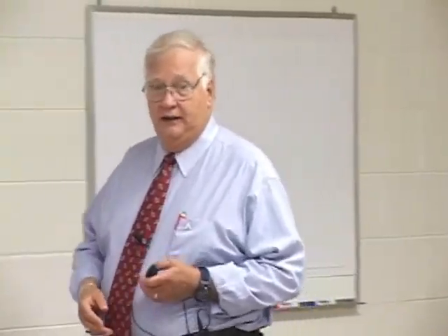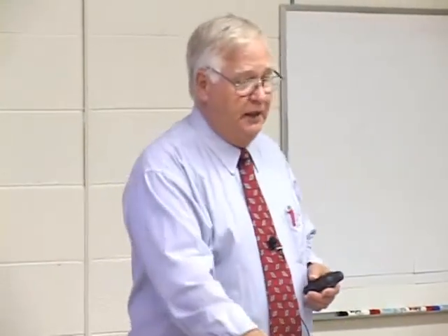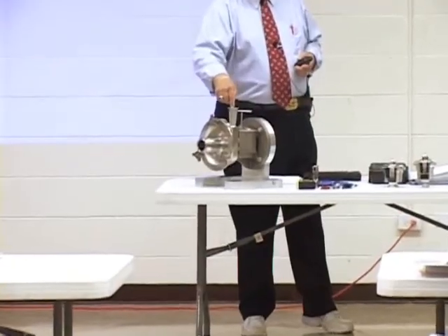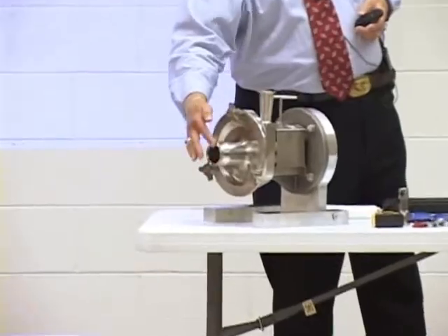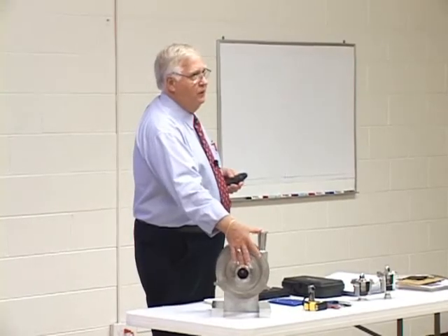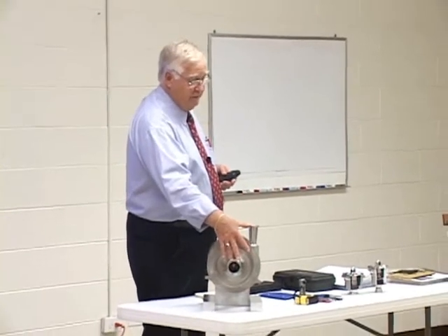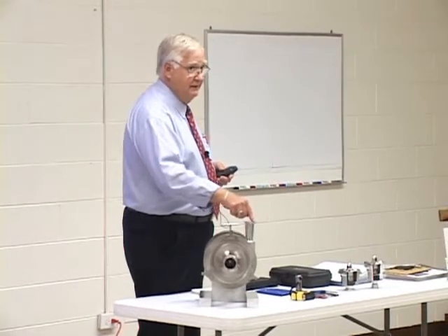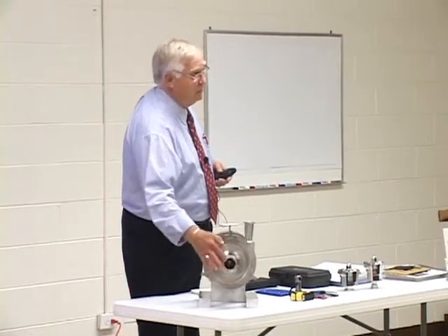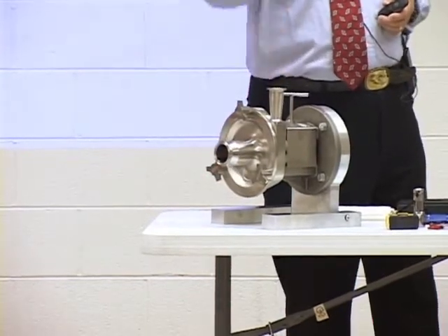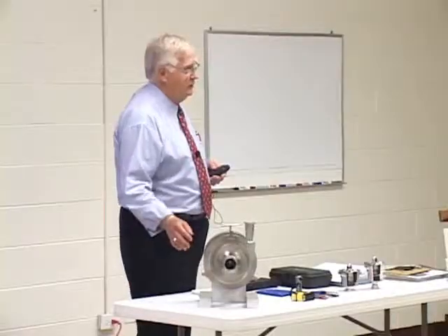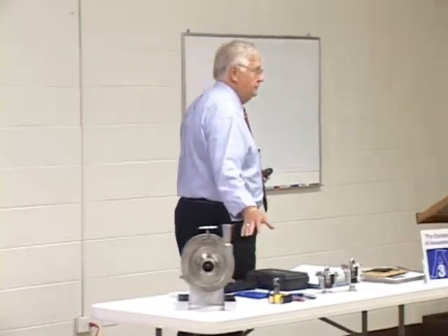In most cases, a good example of a boundary on a piece of equipment like the pump, the boundaries are here and here, inlet and outlet. So for a pump, this gasket and this gasket aren't covered by the pump standard. They're covered by something else, and the pipe coming off of it and the pipe going into it are not covered by the pump standard.